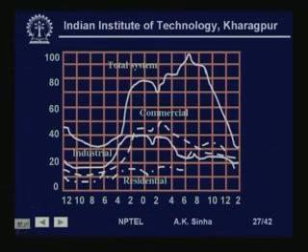So, when you switch on a supply, immediately this power comes by getting extracted from the kinetic energy of the rotating mass, and because of this extraction the speed of rotation will slow down, that is, the rotating mass will experience some retardation. So, this is what we see in terms of change in frequency, or reduction in frequency. Whenever load increases, there is a reduction in frequency.